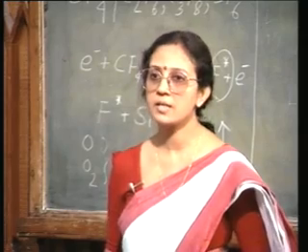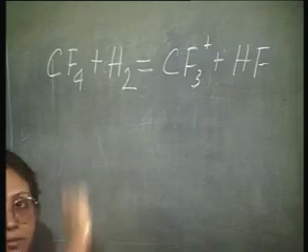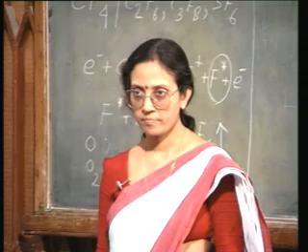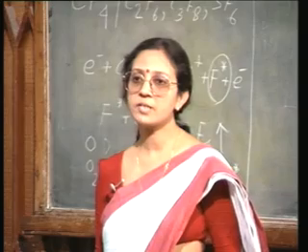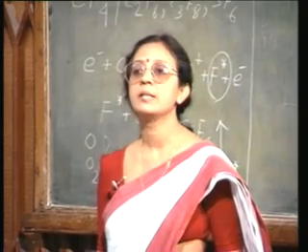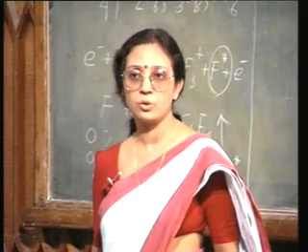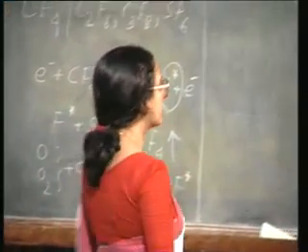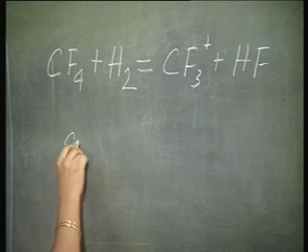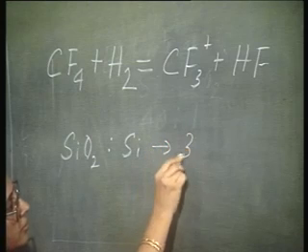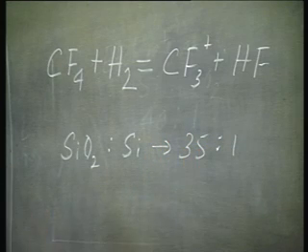Fortunately, silicon dioxide is also etched by this. Right? So, the etching of silicon dioxide will progress, whereas the etching of silicon will get suppressed, and by doing so it is possible to obtain a selectivity of silicon dioxide over silicon of 35:1.